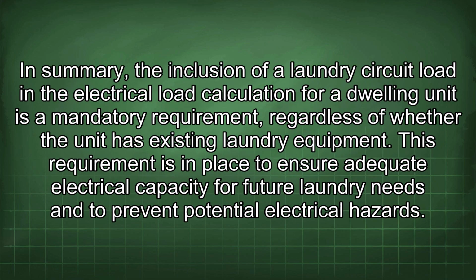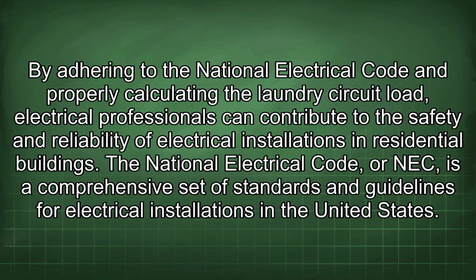In summary, the inclusion of a laundry circuit load in the electrical load calculation for a dwelling unit is a mandatory requirement regardless of whether the unit has existing laundry equipment. This requirement is in place to ensure adequate electrical capacity for future laundry needs and to prevent potential electrical hazards. By adhering to the National Electrical Code and properly calculating the laundry circuit load, electrical professionals can contribute to the safety and reliability of electrical installations in residential buildings.